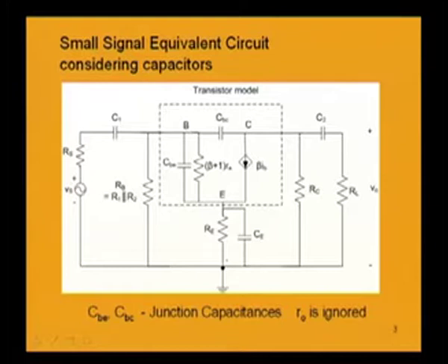So in the denominator of this voltage gain expression, we have minus beta RC parallel RL divided by beta plus 1, small re plus capital Re, because this Re is coming in the denominator. So if the denominator is now higher, overall voltage gain will be lesser.